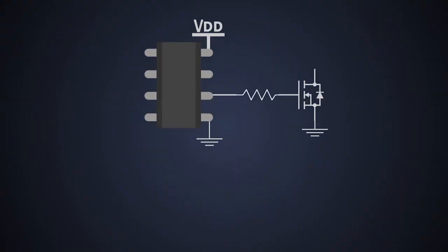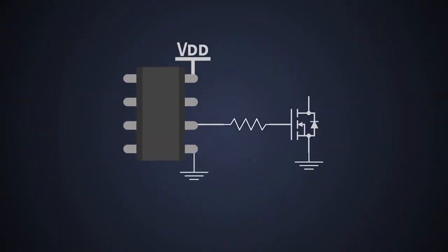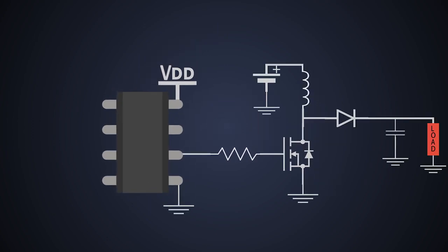When speed enhancement circuits are mentioned, we should exclusively consider circuits that speed up the turn-off process of the MOSFET. The reason is that the turn-on speed is usually limited by the turn-off or reverse recovery speed of the rectifier component in the power supply. The fastest switching action is determined by the reverse recovery characteristics of the diode and not by the strength of the gate drive circuit. This is the most famous misconception.